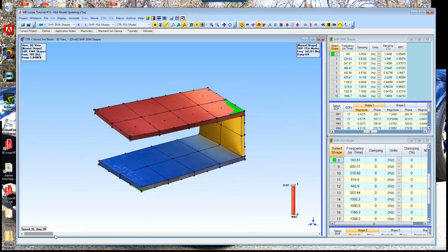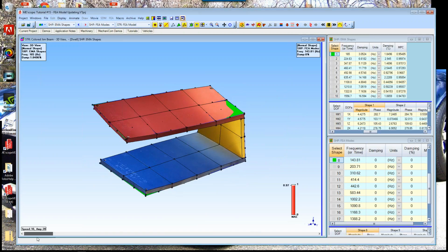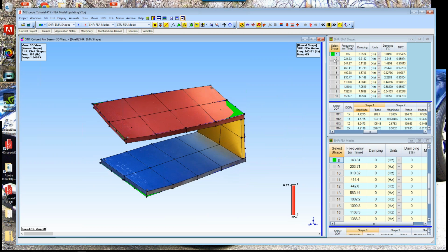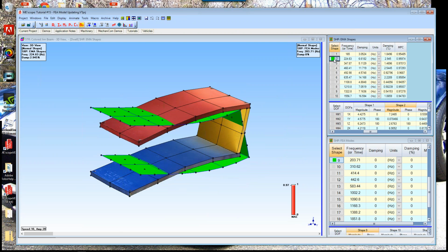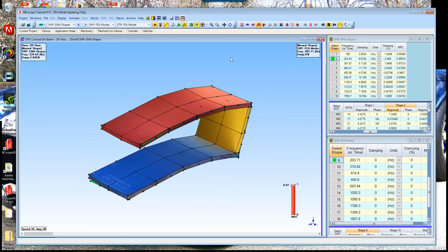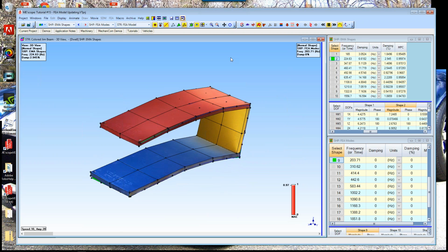so you can see from the animation that basically the FEA model lines up perfectly with the EMA mode shape. So let's click through here. Oh, and there's a phase, so I need to go back here and unflip the phase, and there they line up again.